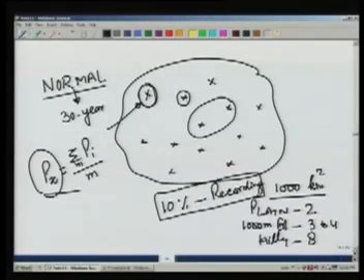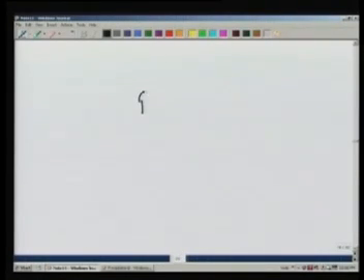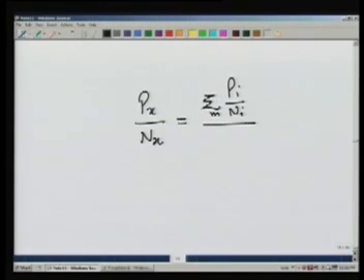So if we are missing the precipitation at this station on May 18th, we can estimate it based on the precipitation on that day for all the gauges and their normal values. So the formula which we use in this case takes care of the variation in the normal rainfall at other stations also. So it's a similar formula, but now instead of estimating the rainfall, we estimate the ratio of the rainfall with the normal rainfall, and that way we can estimate what is the missing value Px.